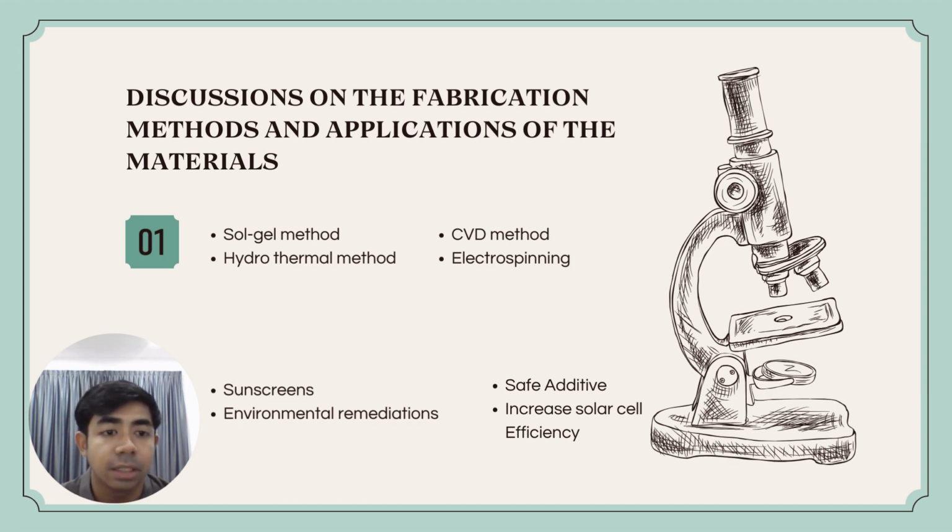And the next one is the CVD method, also known as chemical vapor deposition. Titanium-containing precursors are vaporized and then reacted with oxygen to form titanium dioxide thin film on various substrates. This method is particularly useful for producing uniform and adherent coating of titanium dioxide on complex surfaces. CVD is widely used in the semiconductor industry for fabricating titanium dioxide thin films with controlled thickness and composition.